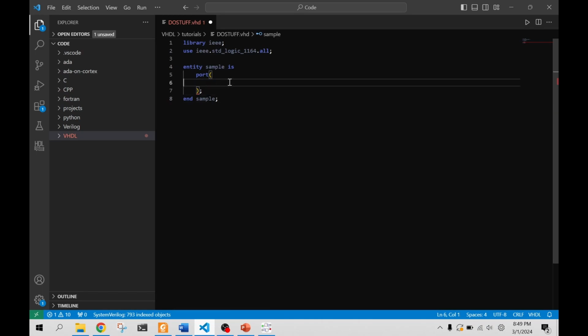Here in the ports, you know how you would declare your variables in C++, outside global variables? Well, these are like declaring the pins of the thing. So the entity is, if you're looking at the integrated circuit from the outside, all you're ever going to see is the pins. We have 2 input pins, 1 output pin. And then this is just defining what the pins are called and their functionality. Nothing about how the internal circuitry works.